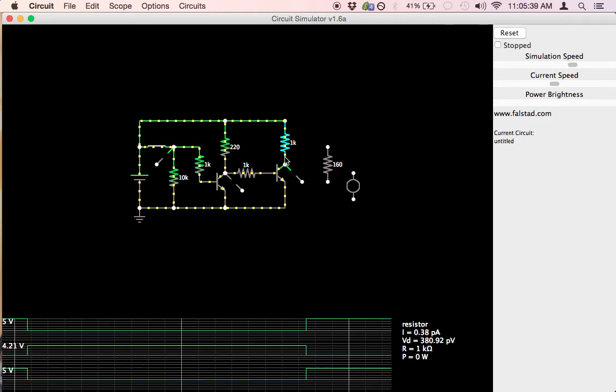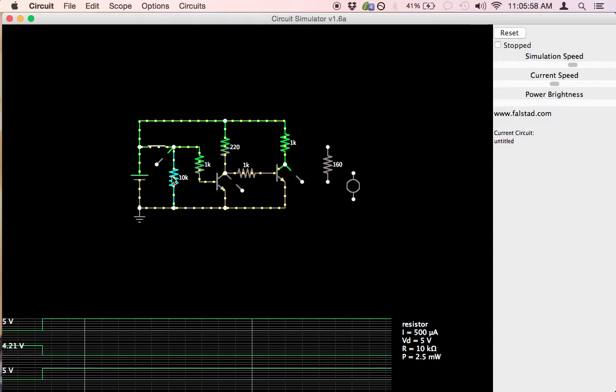So we've got a lot of resistors going on here, and I know it can be a little confusing, and there's different names that we use for them. This first 10K resistor is just a bleed resistor. It's designed to dissipate a very small amount of leakage current out of the base of the transistor. It's probably not necessary in a lot of circuits.